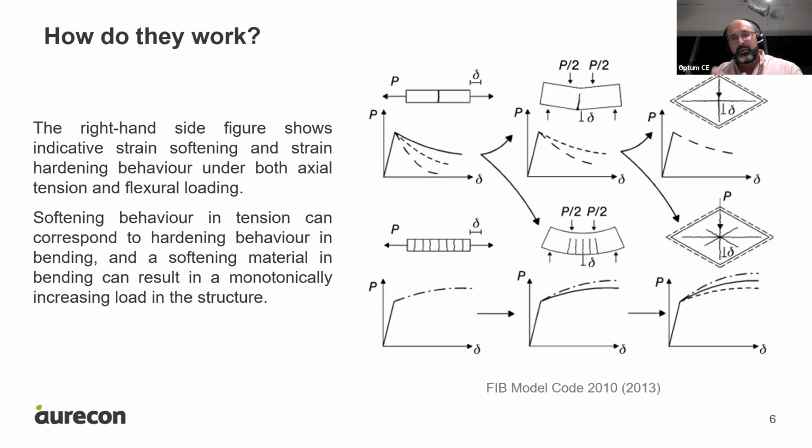And this is very important for one of the examples we're going to show, because of the relevance of the boundary conditions, which might impose different behavior post-cracking. I'm going to really focus on one of our examples, on the concept that we can get much better ductility when we consider the appropriate boundary conditions, in terms of either fixities or loads.